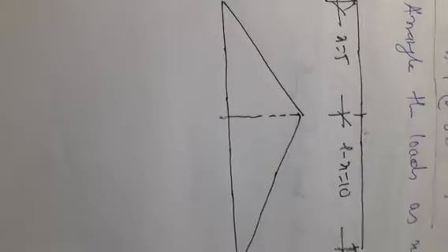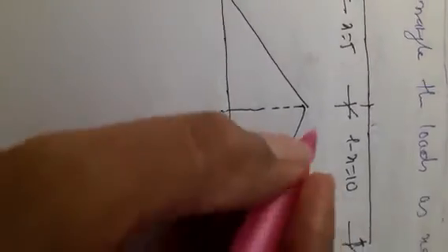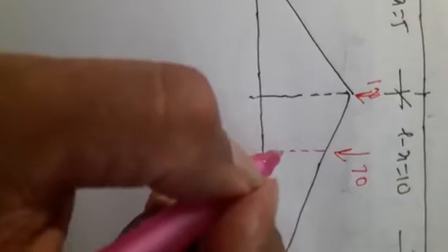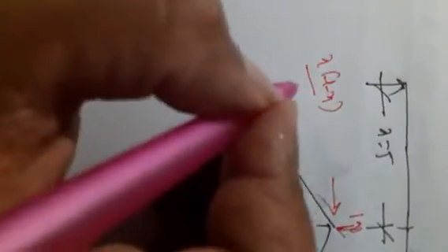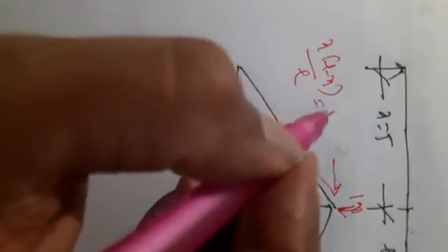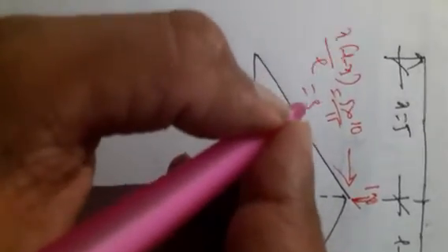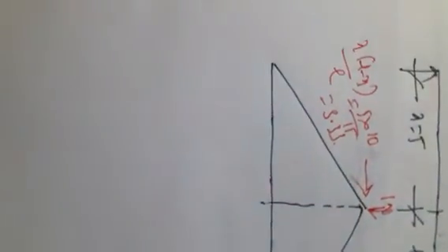If the two loads are different, here 100 and 70, so put the 100 load exactly at the required point and the 70 load wherever it comes. So let this ordinate be y. Now this ordinate is given by the equation x into L minus x by L. So x is 5, L minus x is 10, divided by 15. So you have the answer 3.33.